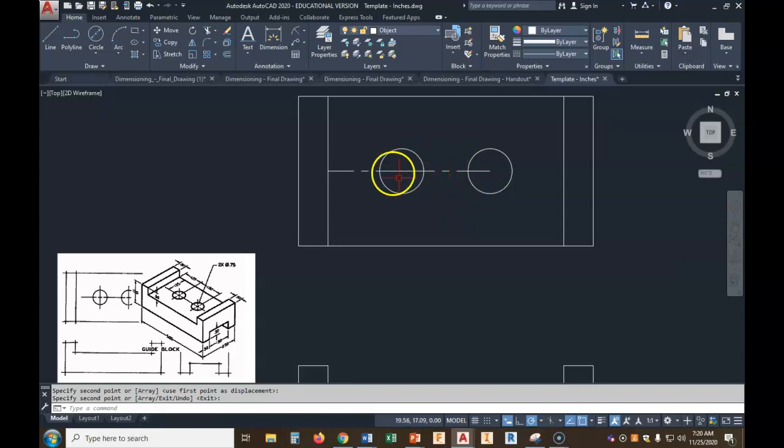Now, these are 2 separate lines. We don't need that. Just click, drag across both of them. You'll drop down here and hit the join button. Now they're one line. Okay? So remember our distances. The center line should stick 1/4 of an inch out past the circular feature. So I'm going to grab it, drag it back to here, drag it back out, 0.25. Now, these are on the same plane, nothing between them. I would like to keep that for reference. So now I'm going to drag over 0.25 there.